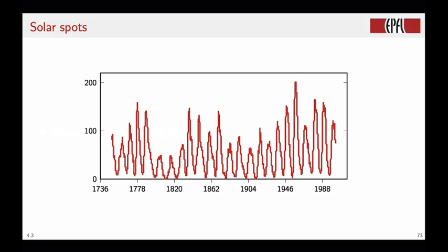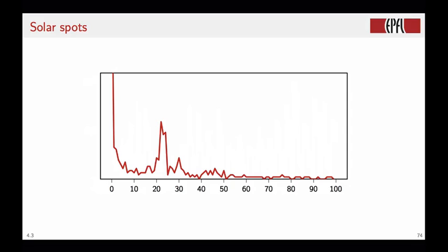And as we plot this data, we see that there is an oscillatory behavior. We are interested in finding out if there's any fundamental periodicity in solar activity, so we can take the Fourier transform. The sunspot time series is a real signal. Now, if we're interested just in the magnitude of the DFT coefficients, you remember we need only show the first half of them. Even so, if you look at the first 1500 coefficients, you see that after the 100th coefficient or so, their magnitude becomes too small to be relevant. So in this plot, for clarity, we just show the first 100 DFT coefficients in magnitude.